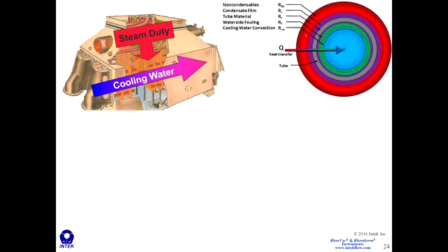But once it makes it through that layer, there is a condensate film. For this condensate film, you can use Nusselt equations, Nusselt coefficients and analysis to determine the heat transfer through that layer. Then there's the tube material, and it has a certain thermal conductivity, so you can calculate that R sub T. Then there's waterside fouling. The fouling could be a calcium deposit, could be manganese deposit, could be mud.